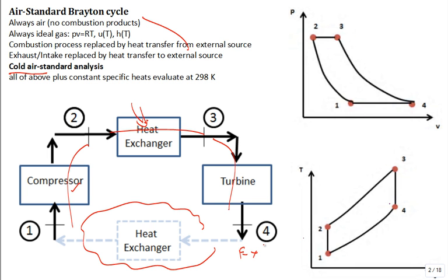We do have a physical compressor. We do have a physical combustor. We do have a physical turbine, but we don't have a physical fourth component. But that's introduced to make it a cycle. Without that, it wouldn't be a cycle. The working fluid needs to go in a loop. That's a cycle. Okay? So then it's cooled in heat rejection, and then back to 1 again.